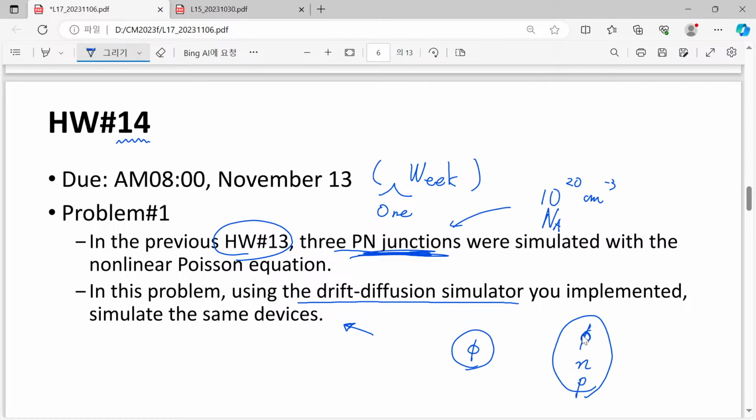The typical issue by students is they sometimes make some confusion in treating their index system. So, for example, if you index this number 10 to 11 or number 10 to 9, then what will happen? Your Jacobian matrix will be just distorted, and your A matrix is completely wrong.